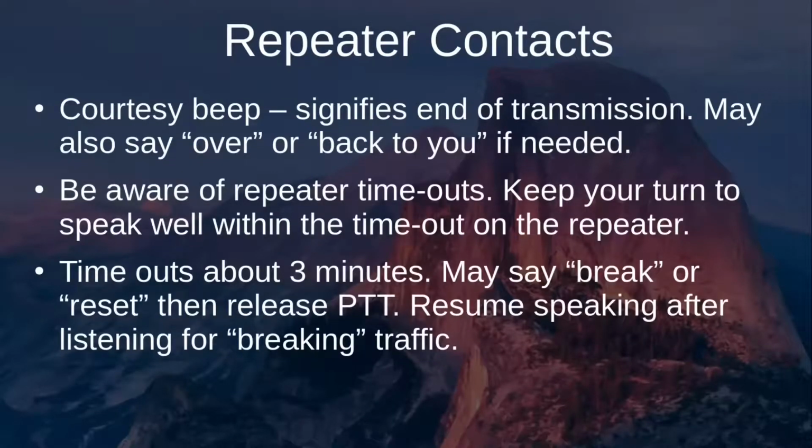A lot of repeaters have what's called a courtesy beep that signifies the end of a transmission. You can also say over or back to you at the end of your transmission. So when you release that push to talk button and you're speaking on a repeater, the repeater will note that your PTT has been released and then come back with a beep, signifying that it's the other party's turn to resume the conversation. But if the repeater does not have that, you can always use the term over or back to you if you need that to facilitate your conversation.